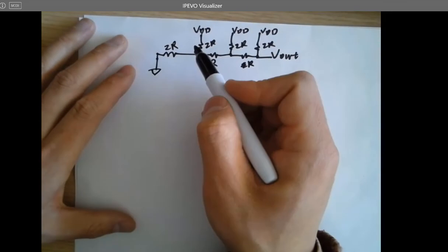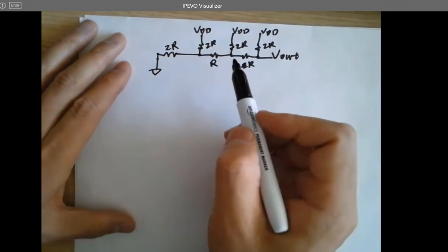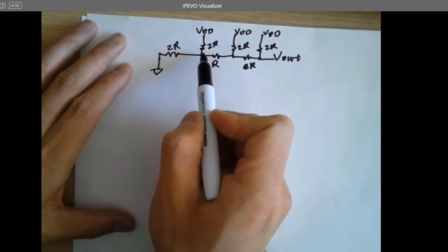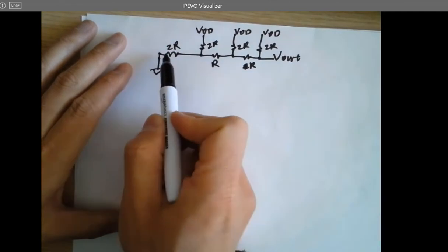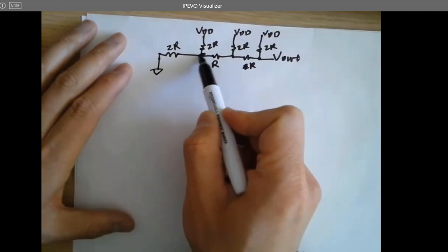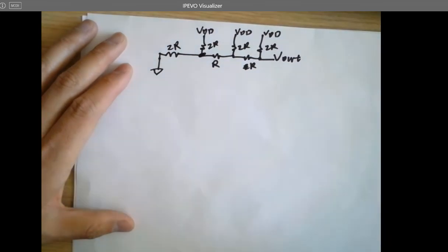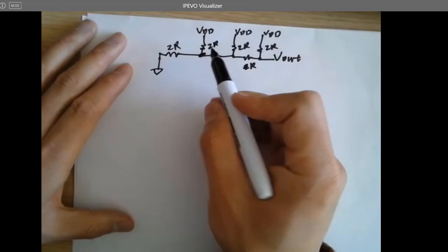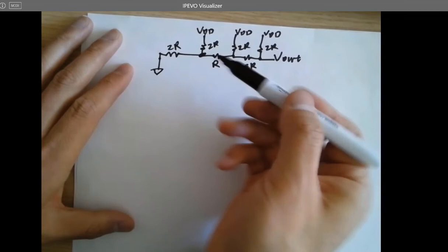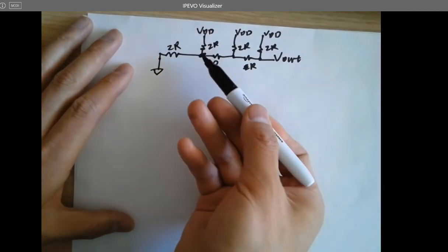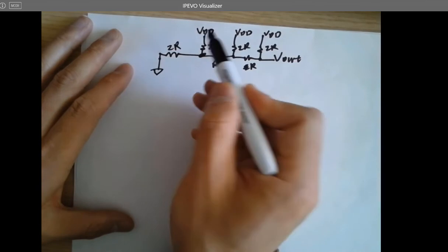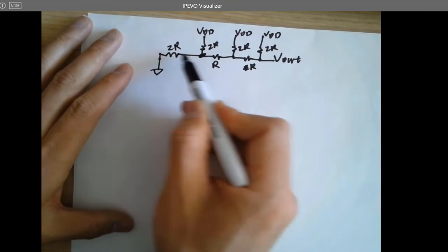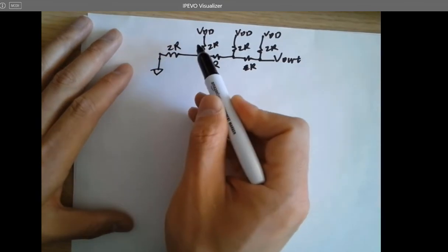Let's take a look at it, all right? Do you understand that this is a voltage source? And here is a resistor directly connected to the voltage source. And here's a resistor connected to the ground. And whatever is behind this point is a load, just a black box. You understand that part? Okay. So we can disconnect everything here and look backwards to find out RTH, which is R. Because when we are looking at RTH, we short the voltage source. So it's going to be ground with two R's, and two branches, it's going to be R, right?